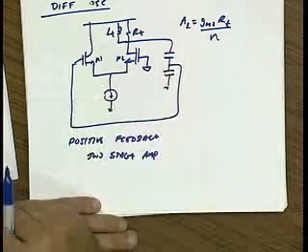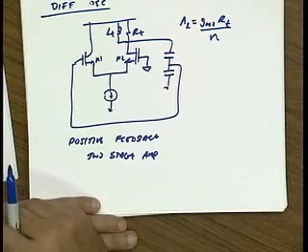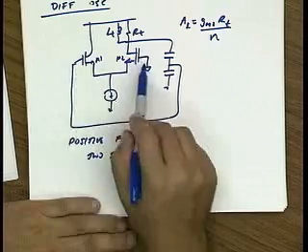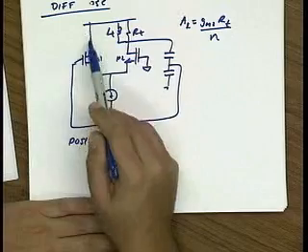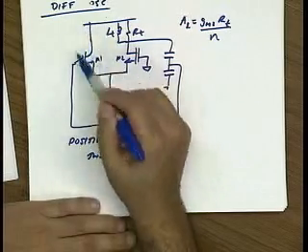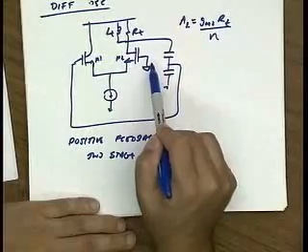Okay, so this is very straightforward, right? Well, if you stare at this a little bit, you say, why use a single-ended signal? Why not actually feed back a differential signal? I'm kind of wasting the other side of this tank. I could also take the output here and feed it back here, right?